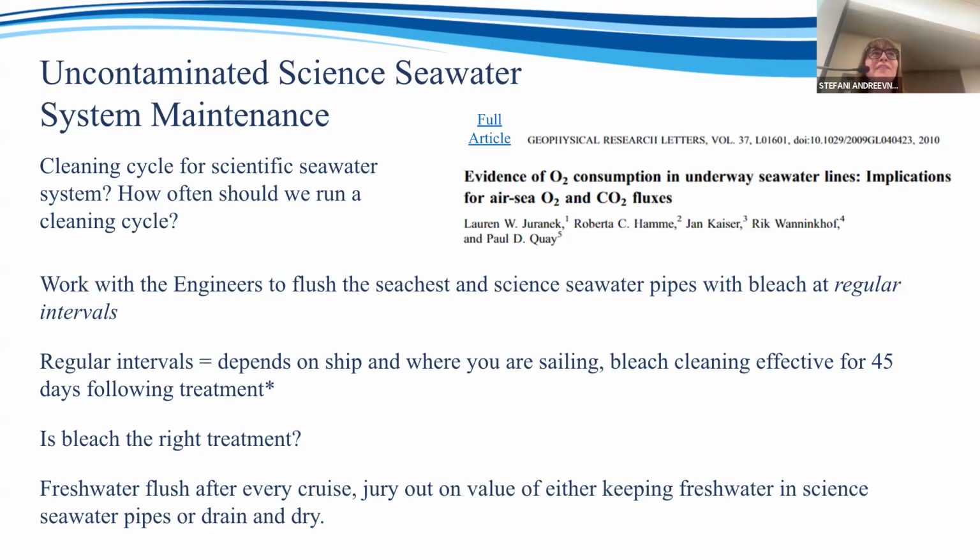So of course, when they say regular intervals, it's going to be highly dependent on where you're actually operating, right? Are you in Hawaiian waters? Did you just go through a coccolithophore bloom? Are you in a coastal zone? How often are your pipes or your sensors getting biofouled, right? So they say, depending on where you are, bleach cleaning can be effective for up to 45 days following the treatment.